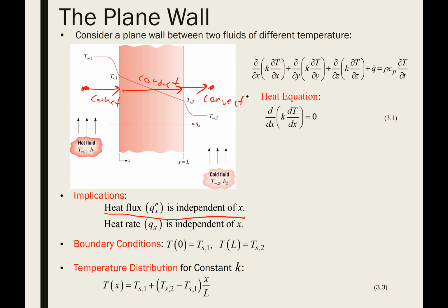We'll keep our circuits relatively simple, but we'll construct what's called a thermal circuit, where we'll consider the convection that has to happen from the left room to the wall. That'll be a resistance to heat transfer. Heat still has to get from that air to the surface of the wall somehow, so it has to overcome this resistance. Then it's got to get through the wall itself, which is going to be a conductive thermal resistance.